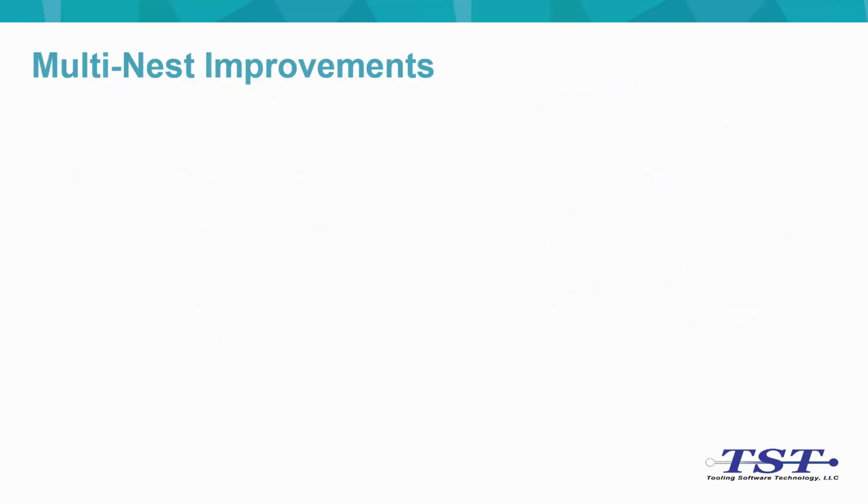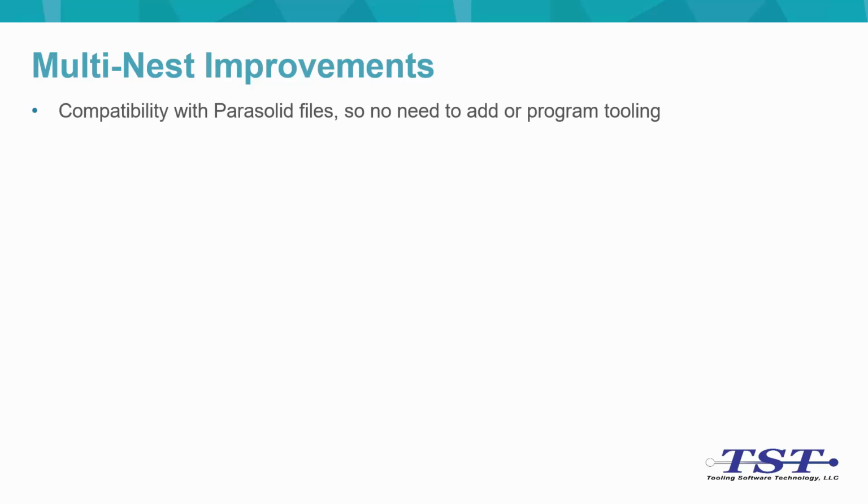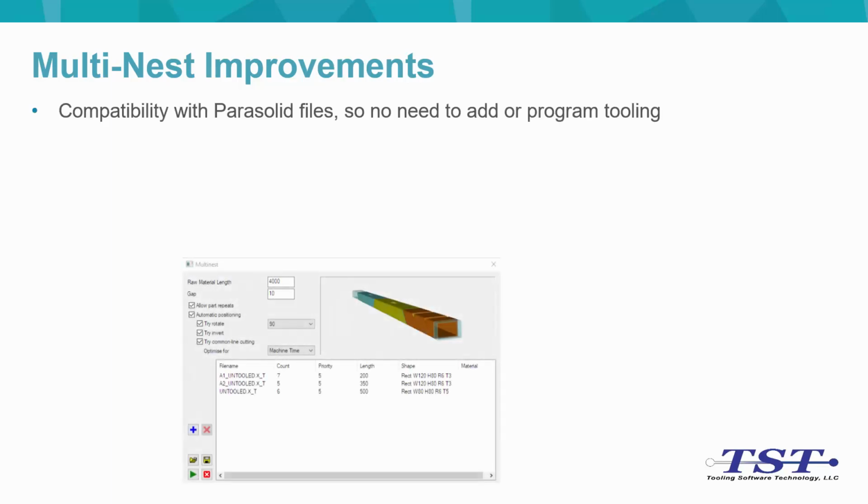There have been some multi-nest improvements. We now have compatibility with Parasolid files, so there's no need to add or program the tooling on the file beforehand. So you used to have to open up a file, add all of your cuts, save it down as a VDM file, and then you had to use that VDM file as part of the multi-nest.